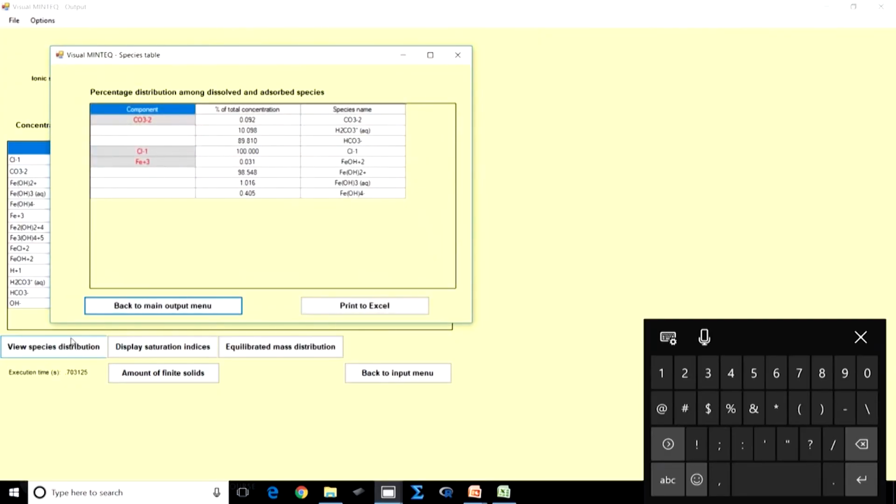Alkalinity means its acid neutralizing capacity, or alkalinity consists of the bases in the form of HCO3 minus and CO3 2 minus. Obviously CO3 2 minus does not play a huge role at 7.3 or 8.3 pH values, right, but HCO3 minus should have been at considerable concentrations. So let us just look at that.